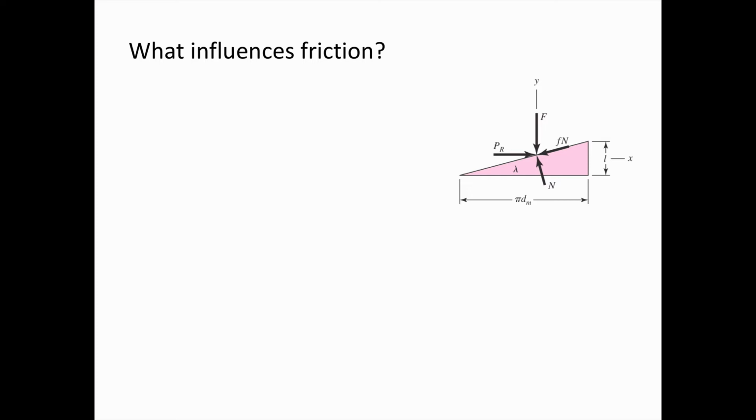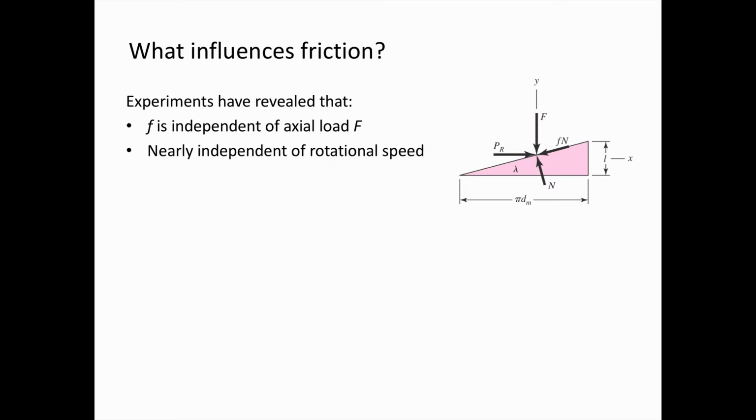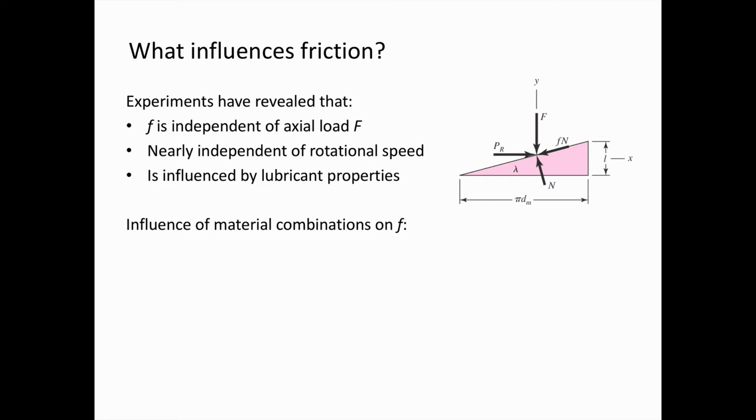Okay, what influences friction? Experiments have revealed that the coefficient of friction is largely independent of axial load for lead screws. It's also nearly independent of rotational speed, but is influenced by lubricant properties. There is an influence of material combinations on the coefficient of friction.